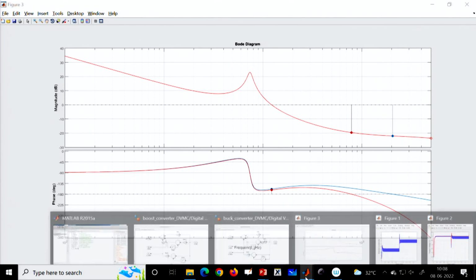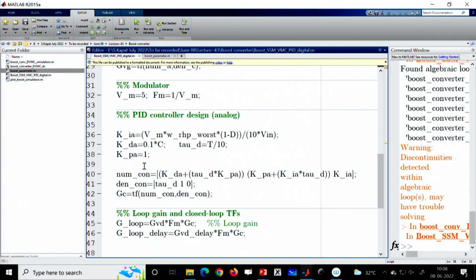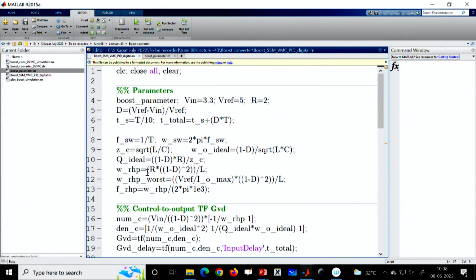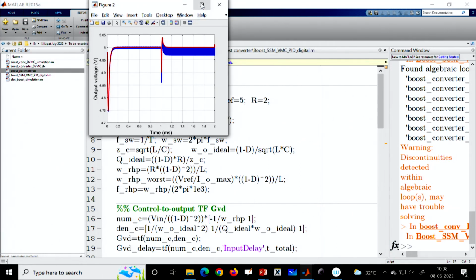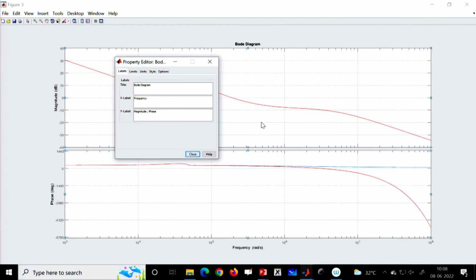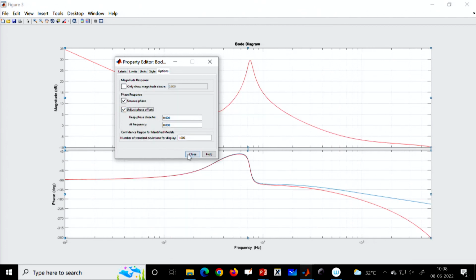That means if we go back, I think we may have to increase this phase boost, because derivative will give some phase boost. So, let us again rerun this and check whether derivative provides some additional phase boost or not. So, now again we are plotting it with unity gain, and we are limiting to 0.5, and we are making a phase adjustment.